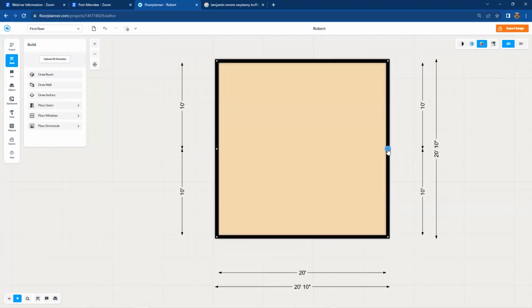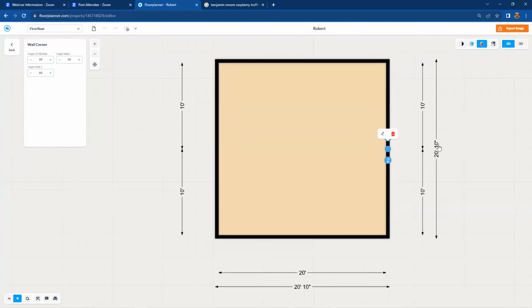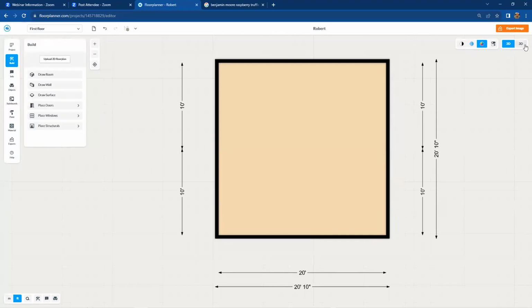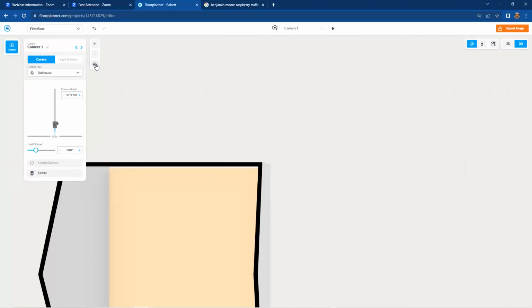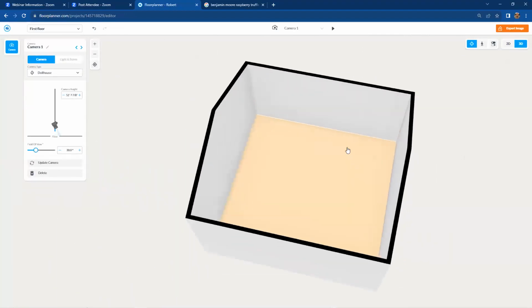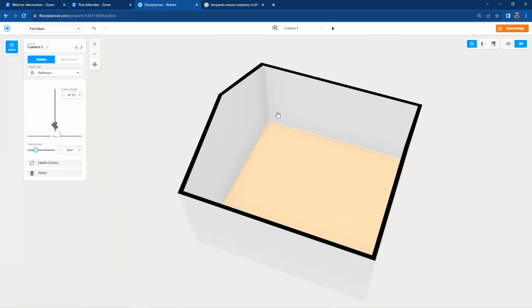Go across the way, I can do the same thing. Now you may have multiple walls coming together at one intersection, so you might have to do it backwards sometimes. So you can actually say wall 2 at that point is 14 feet, and wall 1 at that point is also 14 feet, and hit enter, and then it changes all the numbers also. What we've done now in 3D, zoom extents, is we've changed the wall structure, which is really, really great.